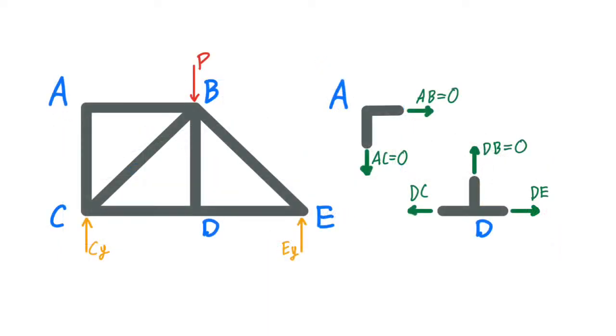Here is a simple truss which has several 2-force members. For the first rule, we will look only at the forces in members at point A. If we sum the forces in X, the only force present is AB. So since it is in static equilibrium, AB must be 0. The same will be true for AC when we look at the forces in Y. This will establish the first general rule we can use to determine 0-force members. If at any joint there are only 2 members with no external forces or loads, and the members are not collinear, both are 0-force members.